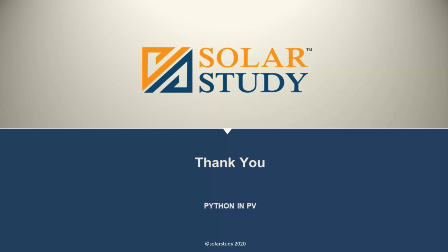In the previous lecture we got some data based on the data sheet. What we will do here is overcome some of the error and try to get as much accuracy as possible in the plotting. That is done by parameter extraction. If I want to calculate, for example, the series resistance, in the flash test you have seen Rs, Rsh and diode current, and all of that we will extract and plot using the parameter extraction technique.